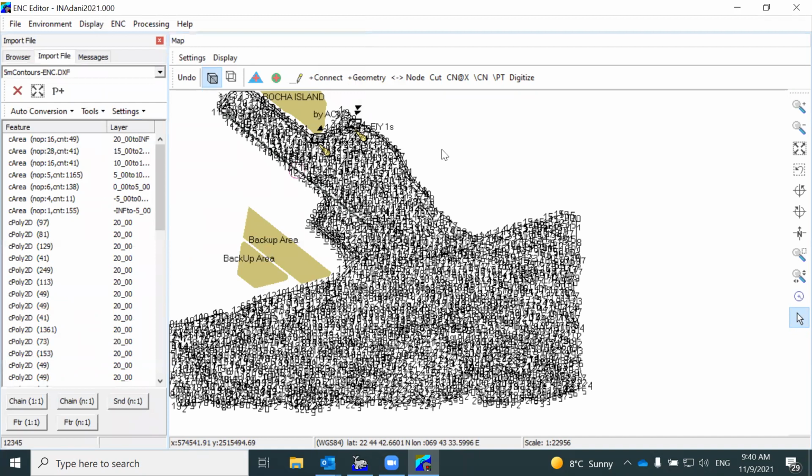If my contours were created in TIN model, and if these contours do not have labels, so they do not have breaks between lines, because the contour should actually be a closed polyline, right? So if it doesn't have any breaks inside, so no labels, that's why we do not use labels in the TIN model, I can just go ahead and use auto conversion here and TIN import.